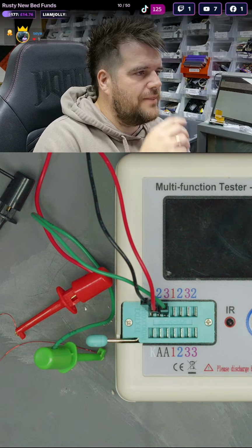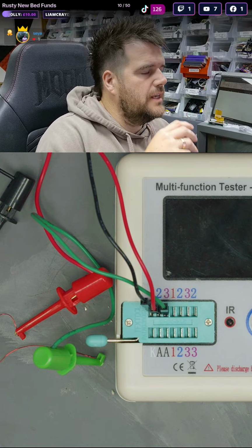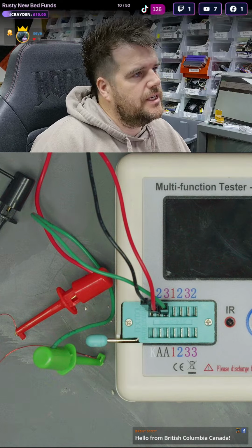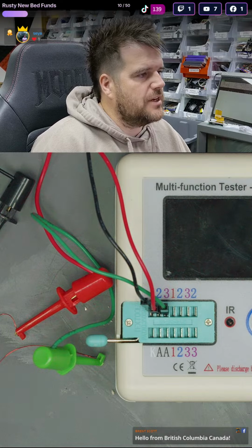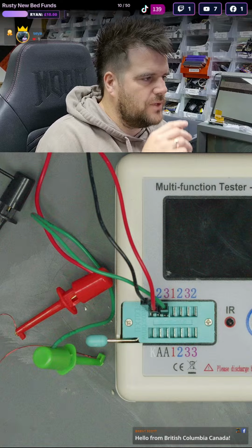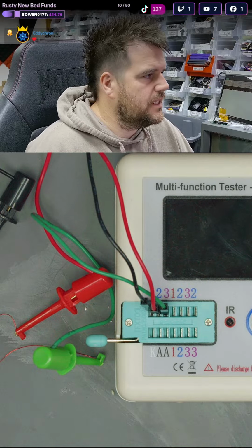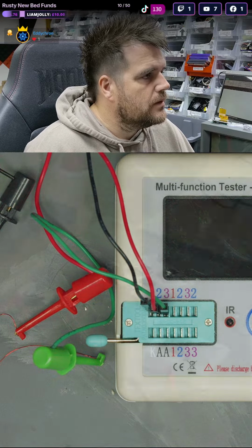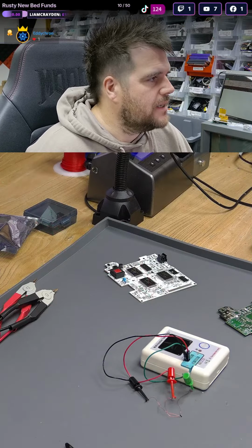I don't think it's a diode. I think what it is is a dual diode, and this test is getting confused and thinks it's an NPN transistor, because that's commonly how it'll test for an NPN transistor. It is by testing if two ways are diodes, and then if you can put current through one way. So I think it can misrepresent the actual component, with it being a cheap tester as well. So let me just do a little bit of digging a minute.